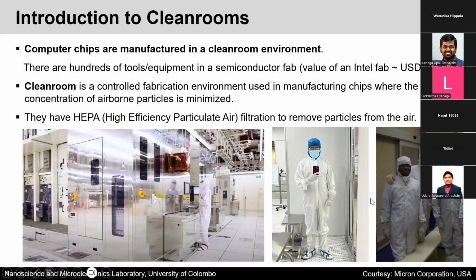So you have to cover your face, your hair, and make sure that none of your particles are being dispersed into the air to make sure that the microchips are completely clean, right? Because you are working with nanometer level devices, and if you are just walking in with just these t-shirts and hair exposed, then these things can actually produce a lot of particles that can damage the chip production.